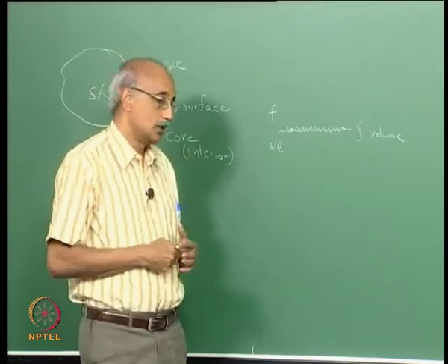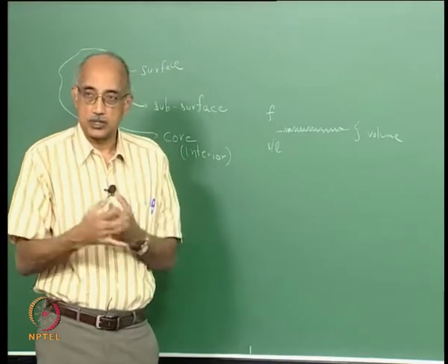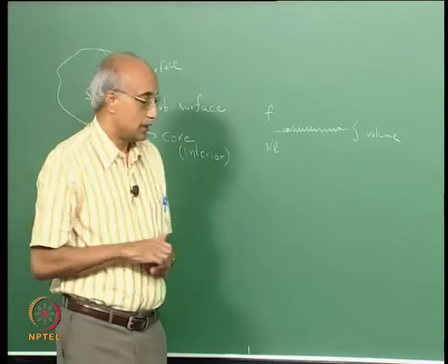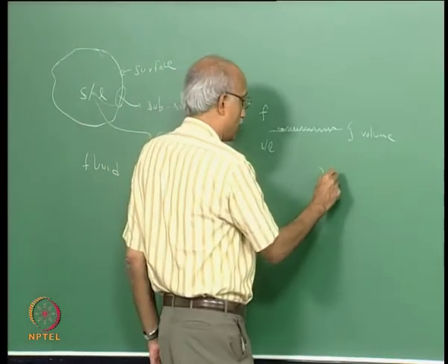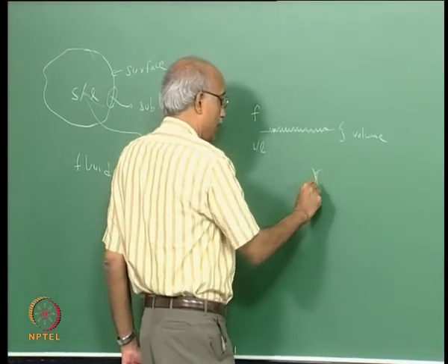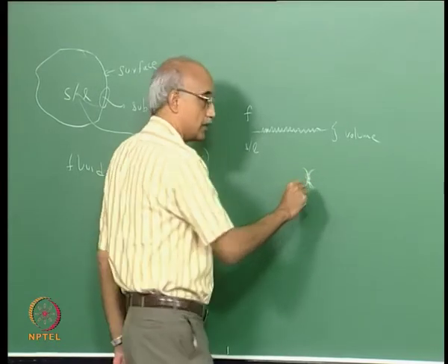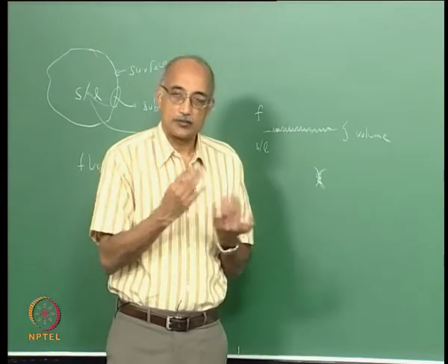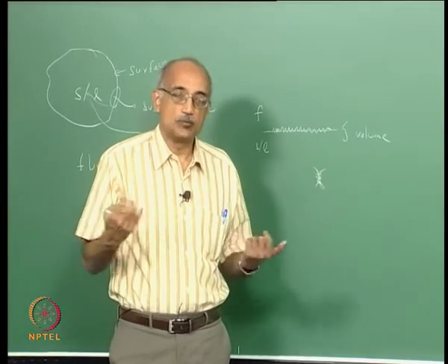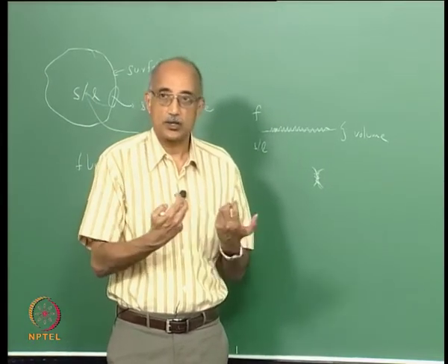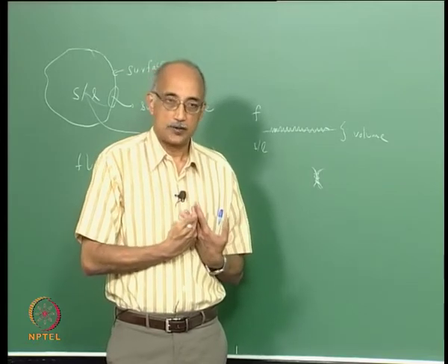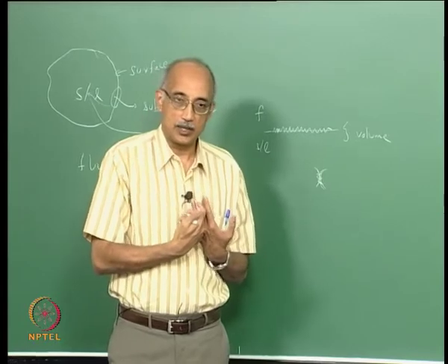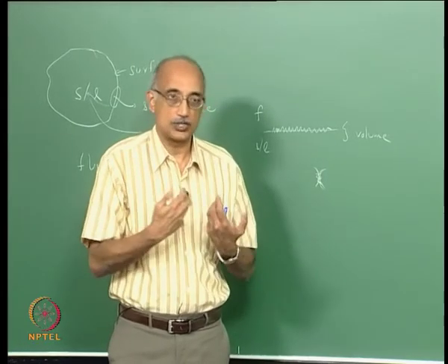And similarly, when you have two particles that are close to each other, which are adhering to each other, the interaction between two solid particles will again reflect the three-dimensionality of the particles. So, depending on the relative roughness of the two particles, you may see more or less interlocking. For example, if the roughness asperities align with each other, you can actually get an increased surface adhesion force.